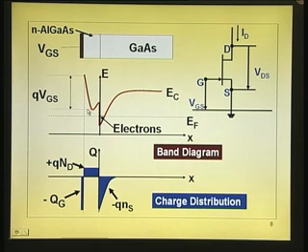See, this is the diagram that we have been seeing. From the left hand side, you can see the conduction band drops down like this. That is because this is the region where the field lines are from the semiconductor to the metal, plus here, minus here. This is a region where electric field is from here to here, plus to minus. Okay.